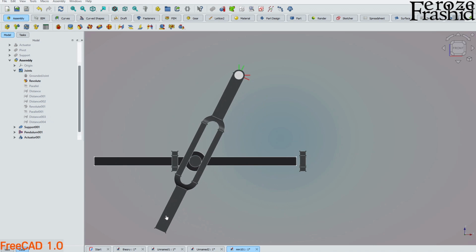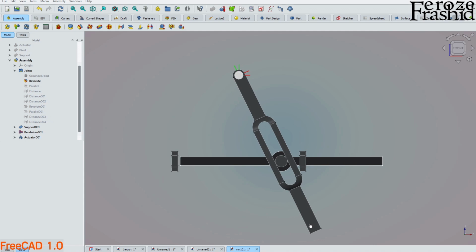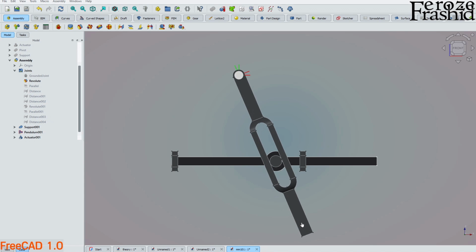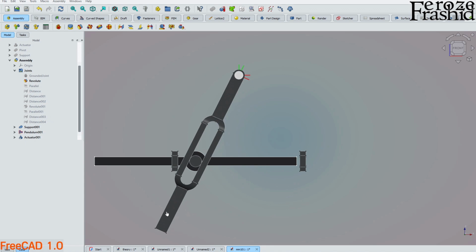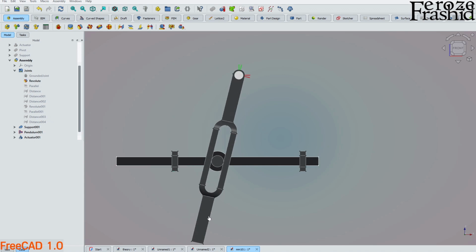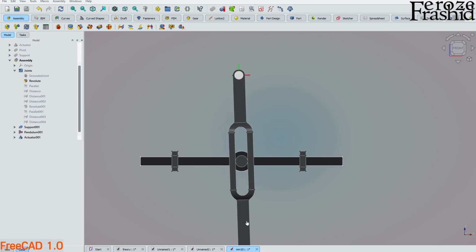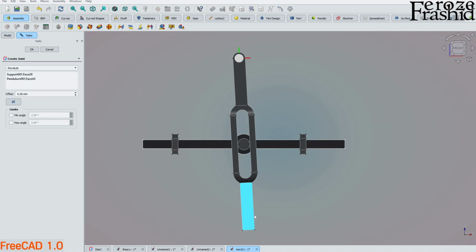Here is, my friend, the mechanical movement 101 as shown in that model, working perfectly. So now we can see that this actuator is coming out of this just like that. We can limit that. We can make that say we don't want this to cross this part, right? So we can do that easily. What we'll have to do is we can do that from here. So there is this revolute joint right there. So we can take that and take the minimum and maximum angles from there.